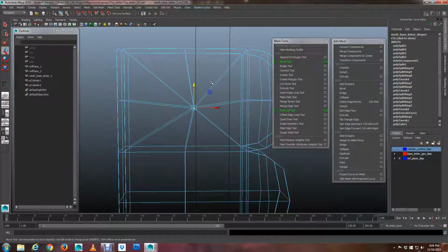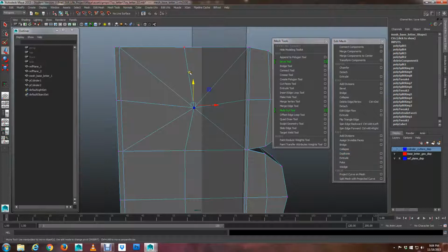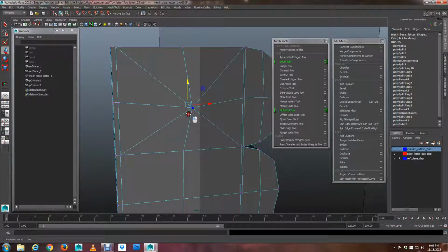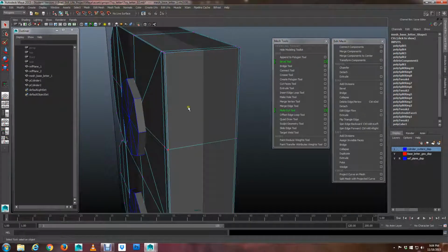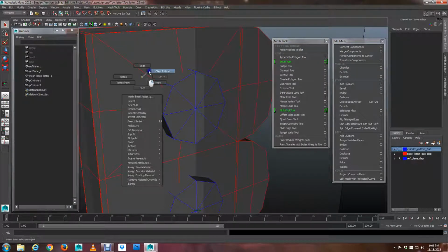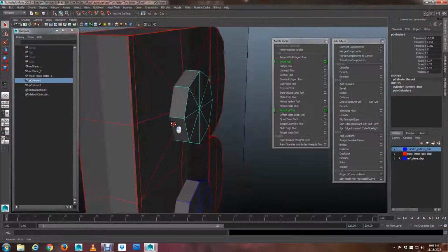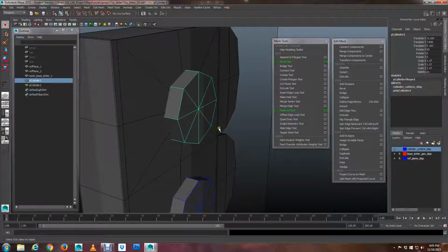Okay. So now that we have this in place, let's jump back to our cylinders and start making these guys. We'll get the cylinders ready to be integrated into the B shape. Okay, so let's jump back to our cylinders. Let's get out of this by going to object mode. Now I'm going to click my cylinders. And I'll put my base letter, this big red B letter, on a reference mode, so I can't select it.